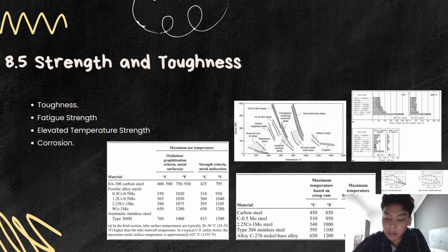Steel is usually associated with strength because in many of its uses it is necessary that steel in one form or another support a load. High strength carbon and low alloy steels have yield strength greater than 275 MPa or 40 ksi and can be more or less divided into four classifications.